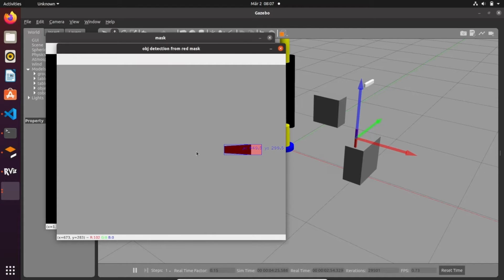Here we go. You could imagine that since this is a normal optical camera, you're gonna see the perception, the depth of our object. And now the object detected using the box inscription is completely shifted, and the center is gonna be shifted as well. Of course, because now the center will not be this one, but this one. And for our application that is not good, because we want the TCP, if we are looking at the 2D, to be placed here, so it's gonna grasp in this position, and we expected the gripper to be somehow here. Okay, so this is not good, and we should find a solution for that.